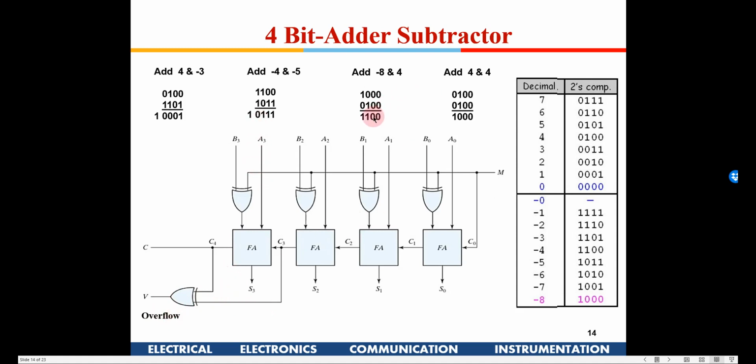Similarly here there is no overflow. 0 plus 1 is 1, 0 plus 1, so it is 0 0, so the output is 0. That means it is valid. So if it is 0, it is valid. Here 1 plus 1 there is a carry, and here there is no carry. So 1 carry and no carry will generate a 1. So the output out here will be overflow.